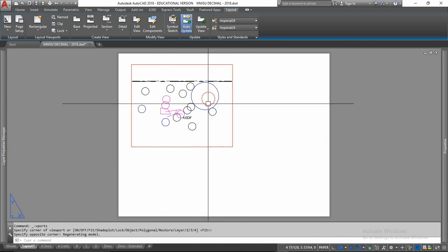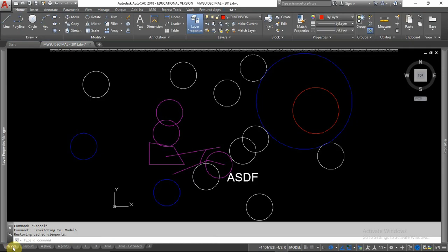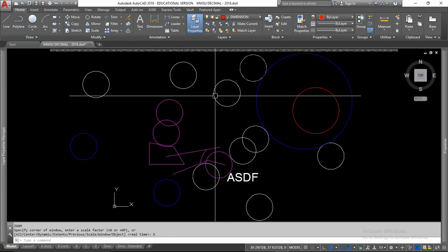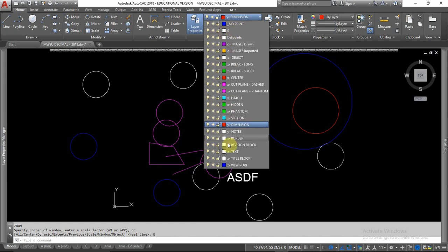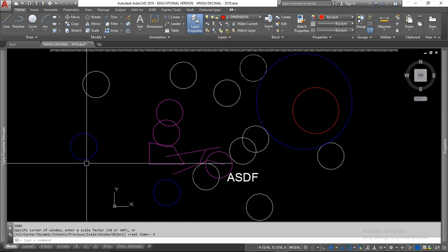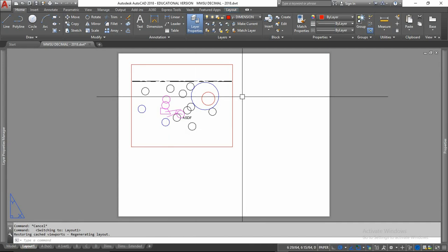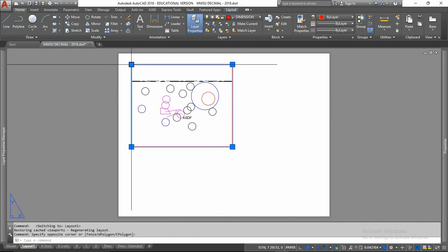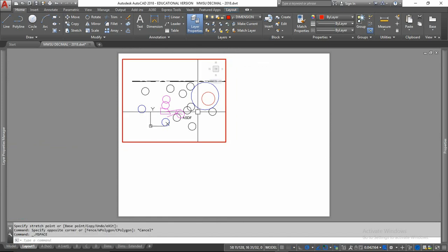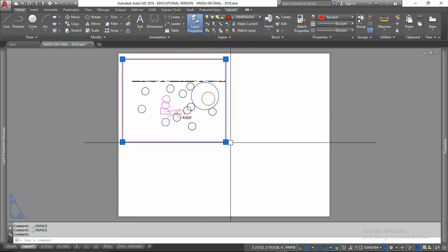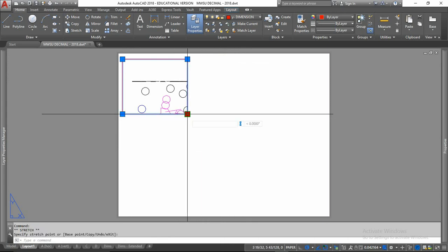Now, you see that there are objects inside of here because in my model space I actually have some objects that I've been creating. Here I'll do a ZE for zoom extents, and this is everything I have. None of my layers are turned off or frozen, and so whenever you create a viewport on a layout, it will automatically zoom to extents in that viewport. Now I've just adjusted the grips, and so that's changed. I can move it up here, which is not a big deal.